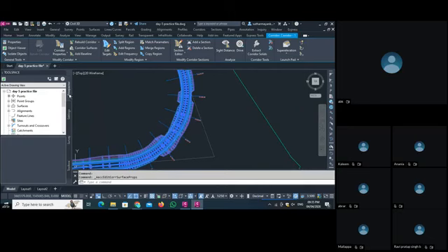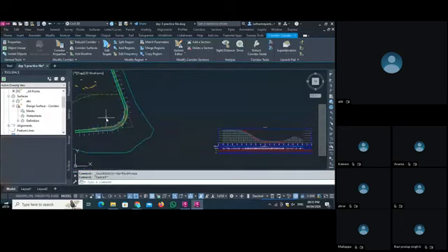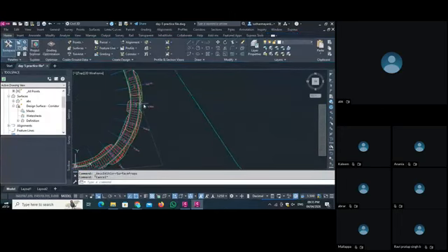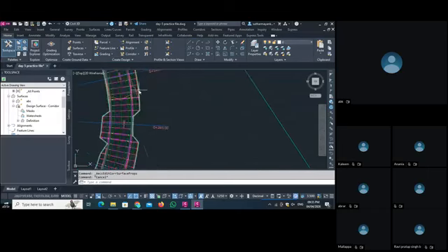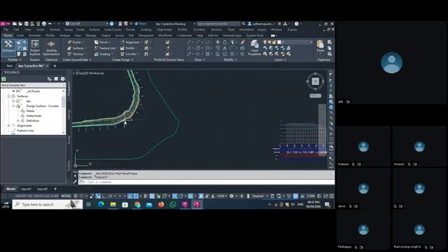You can see your surface from the point surface. See here in surface. First we had only one surface, the ground surface, named ABC. Now we have the second surface, design surface corridor. You can make any changes from here also. We created our surface here. You can see the boundary here also throughout the surface, as I set the outer boundary.